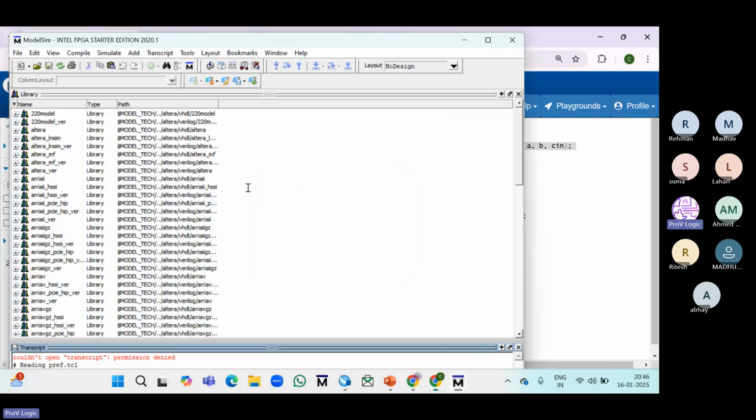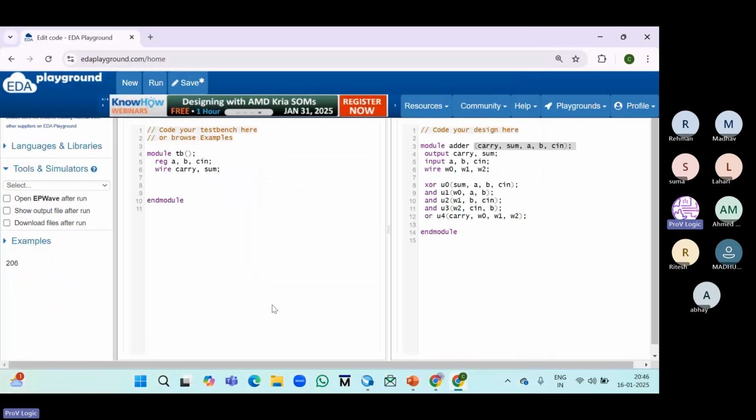So we will get a number of files. In hundreds of files, the design and test bench cannot tell which design is targeting which test bench inputs. That is why we need to make the interconnection here. In SystemVerilog, we call it an interface. Here also we need to do the interface. But in SystemVerilog, we have a complex program which is connected dynamically. Here it is very simple, just a one-line interconnection.